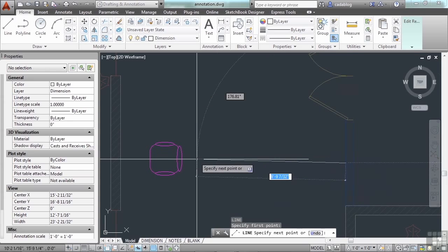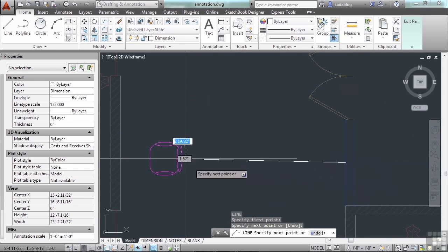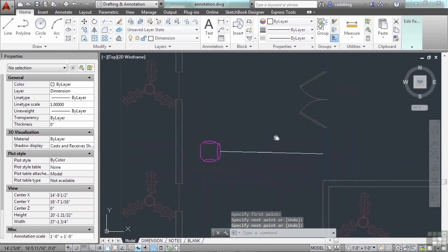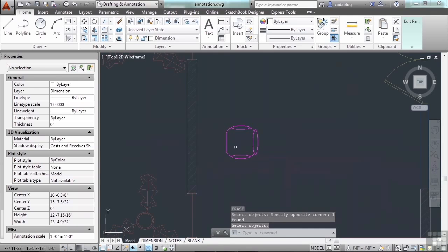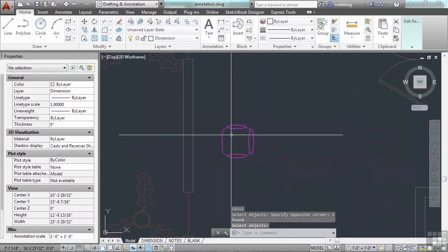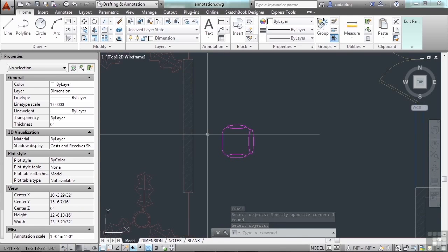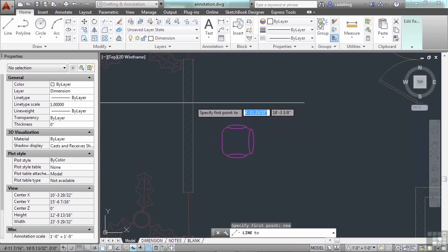What I'm drawing now is going to be a part of the block. This gives you the opportunity to, let's say I want to create a desk with the chair block, but I want to make sure that the chair fits against the wall properly. Start the line command. And I want to put it on this wall.